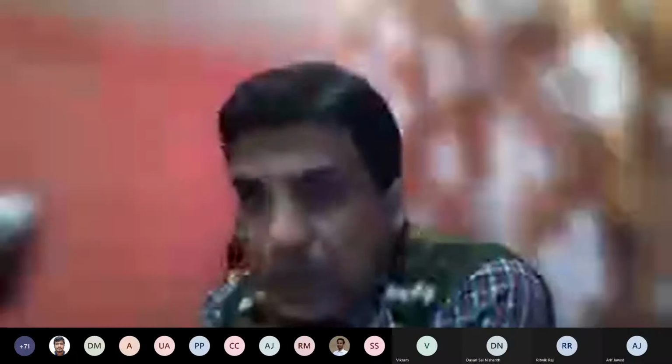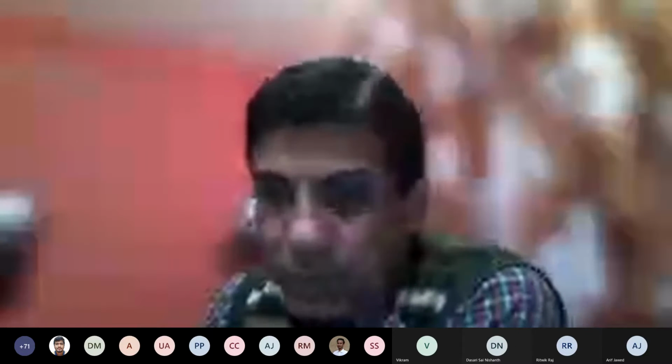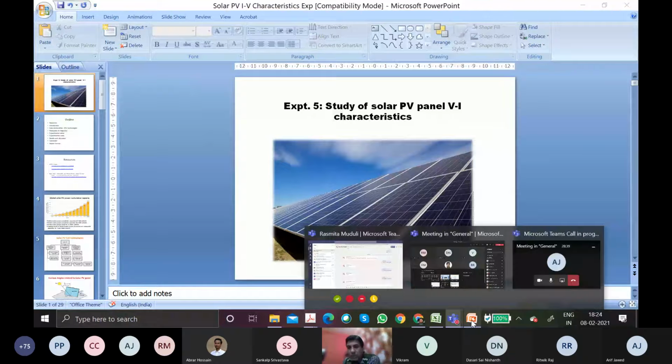Control is a closed loop, and control action is taken. So based on the change in wind velocity, the required change in the pitch angle is made in an actual wind turbine plant. Here it is done manually, so you may think that it is very easy to do that, but it is not like that, actually it does not happen like that.